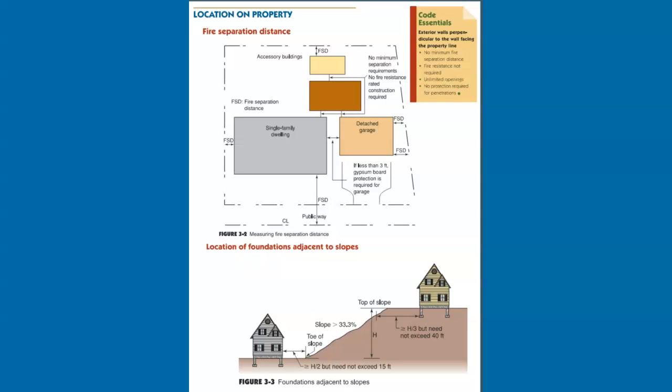Additionally, construction in flood hazard areas must comply with the elevation and design requirements of the IRC or local floodplain regulations. There may also be local or state laws that require grading permits and regulate erosion control, stormwater management and soil conservation measures. A number of other factors may affect site preparation and building design, including high water tables and sloped sites.